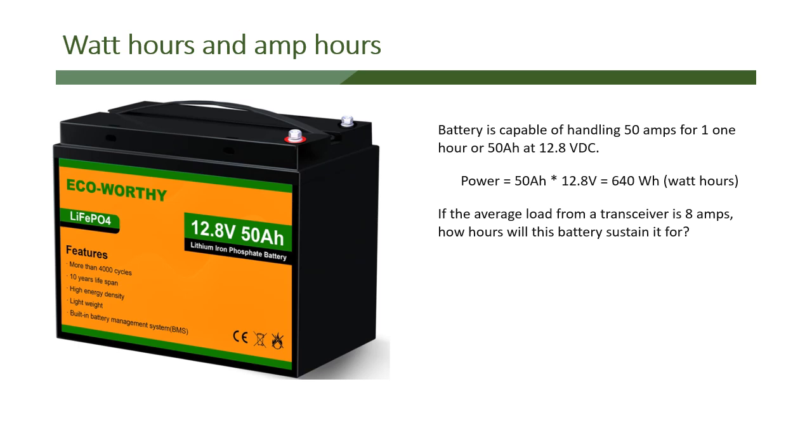So if the average load from a transceiver is 8 amps, how many hours will this battery sustain the transceiver for? So we have 50 amp hours divided by 8 amps, and we get 6.25 hours.